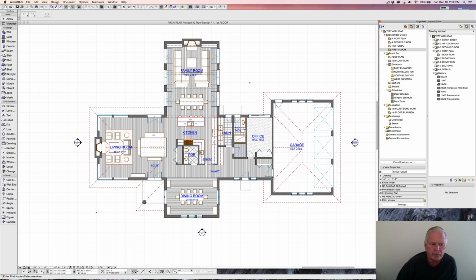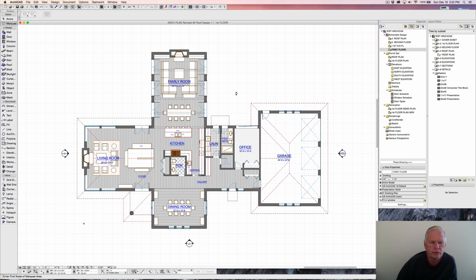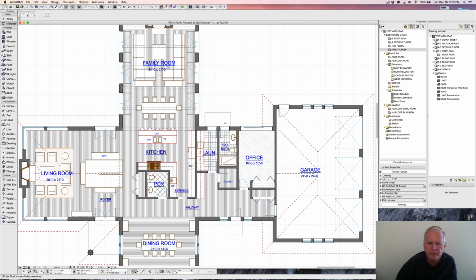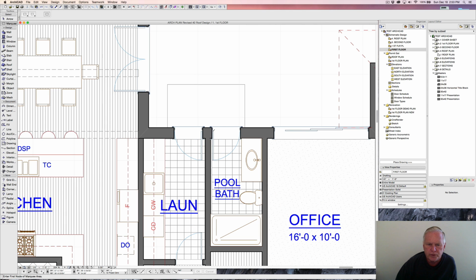And by that I mean we have moldings, brick moldings running around, and the depth of the windows and the walls. And as you see, just for an example, if we zoom in on these doors here, of course you see that their brick mold is outside the wall when in fact it really would be set in, and that door jamb is on the outside edge of the wall, and if that's a brick veneer wall, that would be incorrect.